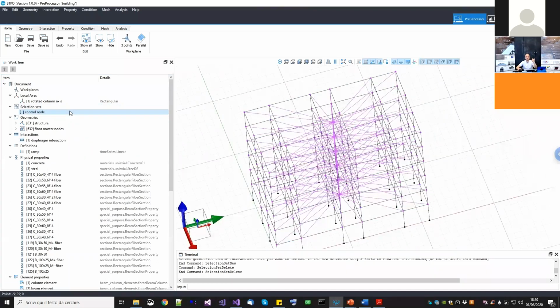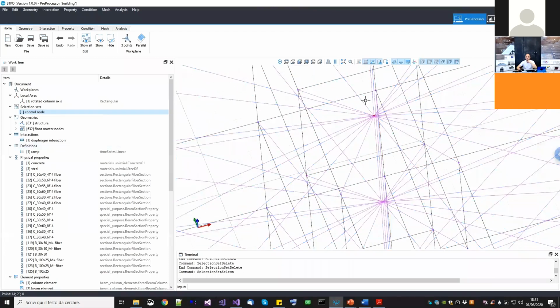First of all, to reuse a selection. For example, in many modeling situations, you may have the need to select a portion of a geometry many times. So instead of going and selecting them all over again, you can do it once, save the selection set and reuse it. For example, just by clicking here and clicking select, you will have your selection already there, okay?